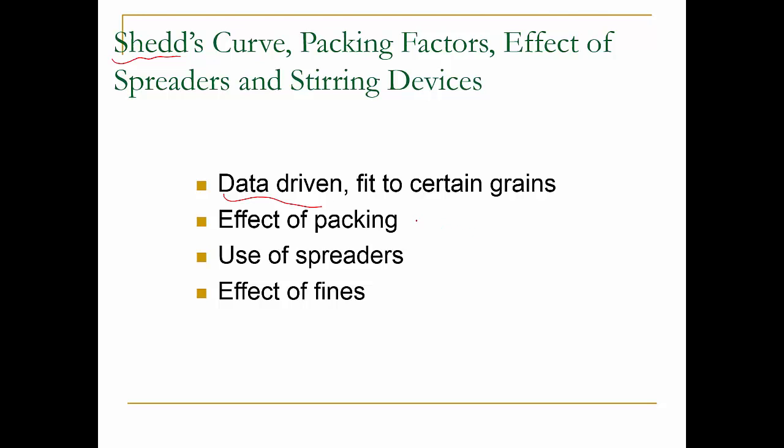And you need to consider the effect of graining, because in the lab you do it with a clean grain, right? Whereas in real life, it's stored about 100 feet high. Therefore, you do need to consider the packing factor. Typically, you multiply by 1.5. We call it a packing factor. So you multiply by 1.5, whatever the values you get, to accommodate for the packing.